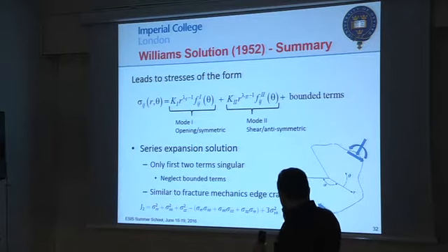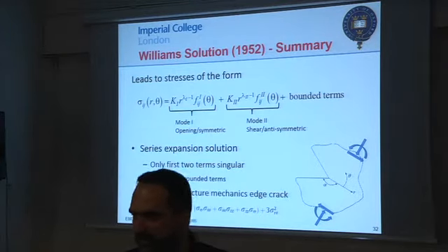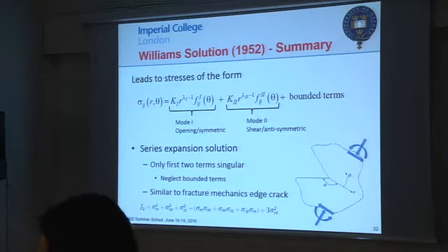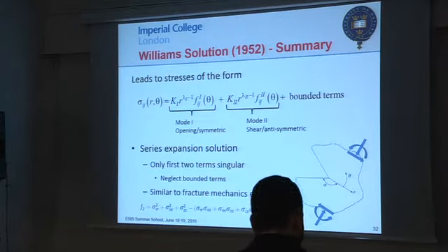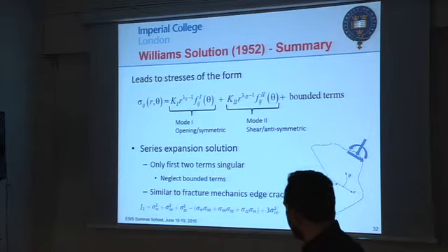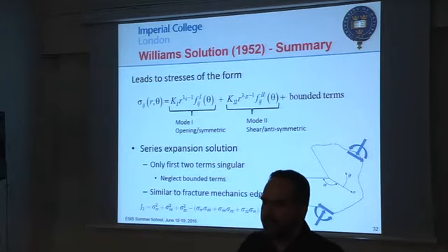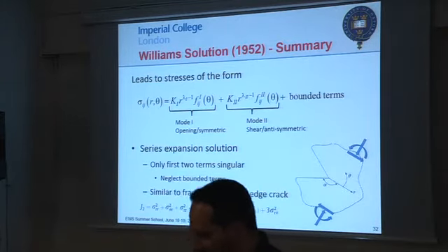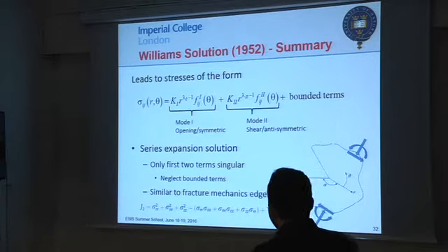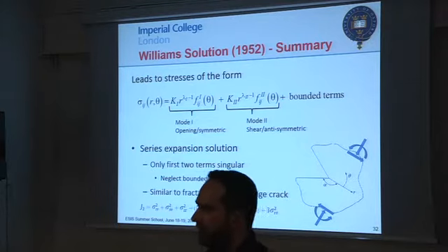Now, one thing we can do is, for each of these stress fields, when you have a stress field, you can define the invariants. So one thing you can define is the second invariant, or the deviatoric invariant of stress, which in polar coordinates is sigma r squared plus sigma theta squared plus and so on. If you have that, you can start plotting and looking at what this invariant looks like.